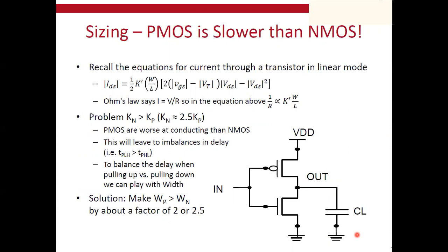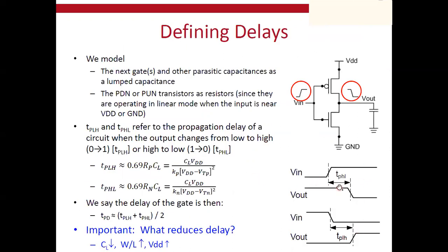So simply, when we consider the capacitance in a logic gate, we are considering the overall output and the input capacitance. Of course, the input capacitance of one gate will act as a load capacitance for the previous gate. That's why the input capacitance is important. The value of the capacitance contributes to the overall delay seen by the gate. So this is a very simple equation that you can use.